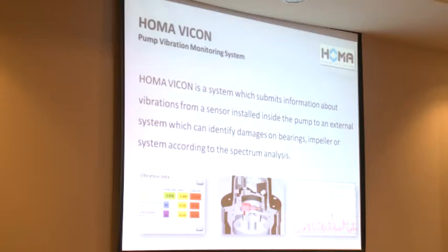is coming from. You can do long-term monitoring, you can save this data on a memory stick, and accordingly do a very good evaluation of what is happening inside the pump. And as I said, it's a pre-alert system, so it also gives you the possibility to interact and to do maintenance, to do exchange of the parts, even before a failure might happen to the pump or the motor itself.